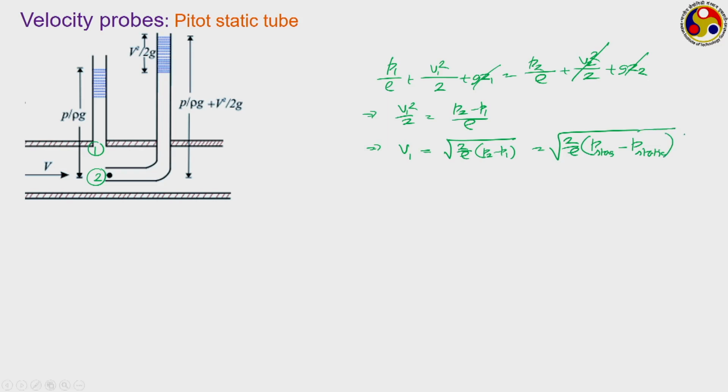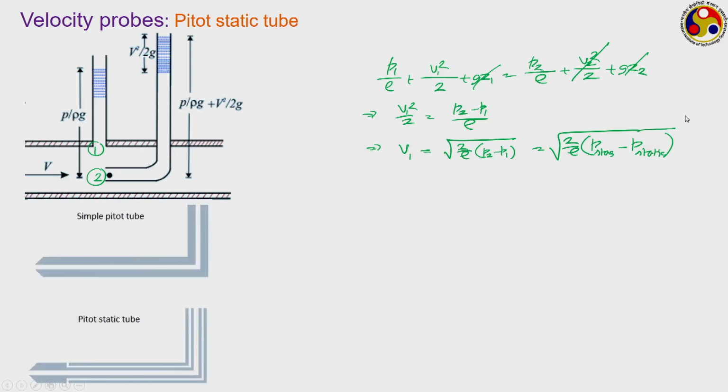So, using just these two piezometers we can get the measurement, or more commonly we can have the pitot tube, where we have both the stagnation probe and static probe mounted with each other. We have already discussed this in more detail. This is more for academic purposes, to let you know that pitot tubes are generally used for velocity measurement instead of pressure measurement.